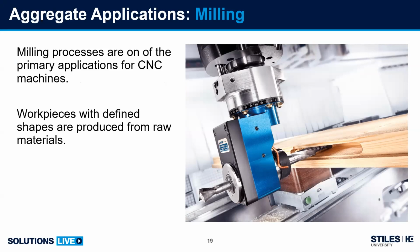Lot of different applications here. The Forte unit is a great one. You can see here it's got a dual output, so coming off the back there, it's an ER16A tool output on there as well. One other thing to pay attention to, we walked through the steps on the aggregates. You can see here's your aggregate tension ring, the torque arm to the body. One unique aspect that this aggregate has, and we're starting to see these more and more as time goes on, is that copper brass looking piping there coming down right near the tool output.